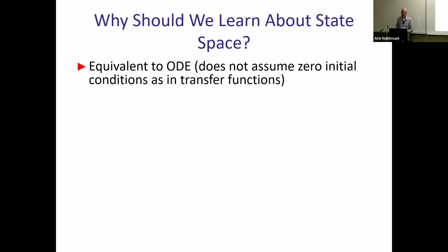Yes? So are you saying if you put it in state space representation, you can't use the nice diagrams that we were showing last week? Not that type of diagrams. Yes, it still will be a controller in the loop as negative feedback, but the controller will be connected to the state instead of the output. So the output will be separate from the state. State will be state, then you get multiplication by some matrix, and then you get output. But the controller connects to the state, not to the output.